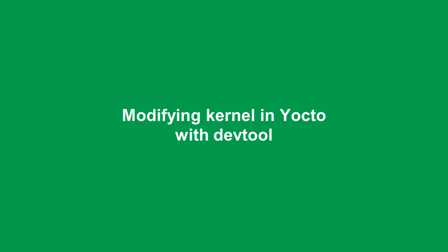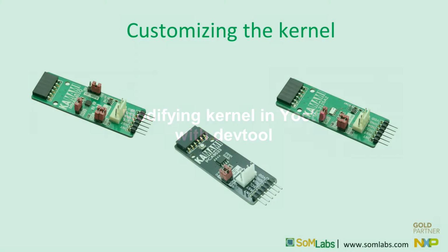In order to run the peripheral modules that are included in the webinar kit, we need the appropriate drivers. The kernel has support for all of these devices, but we need to include them in the configuration file in order for them to be compiled with the kernel sources.